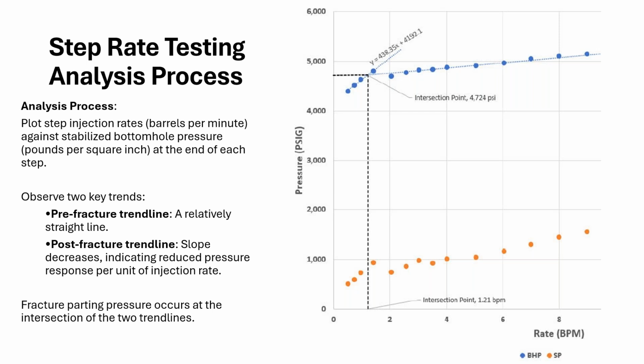Okay, thank you. Next question, what is a recommended practice to start a step rate test when your well doesn't hold a full column of fluid to avoid injecting air? That is always an issue with injection wells that are low pressure or on vacuum, and you have to account for it in your analysis. You have to note that either this is your 0 point on your rate.